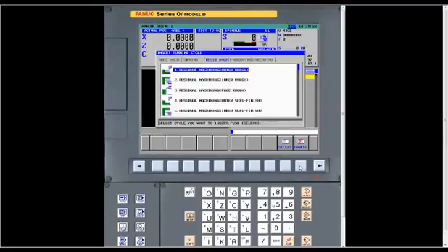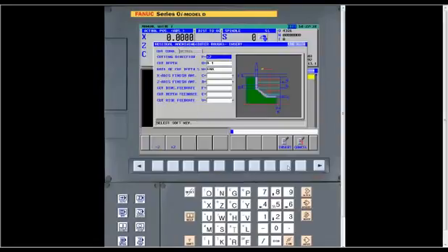The next tab is residual machining. And just to give you an explanation of what that is, say for instance we're turning a part that has a large relief that only one particular type of tool will fit into. What the software does, as long as you have your tools described right, it'll look and see if a tool has clearance to get into that relief. If it doesn't, it'll give you a little message saying residual stock will remain. That tells you that you have to go into this cycle and select that and fill in the blanks just like before. Again, it's got Z minus, Z plus, and it looks just like a rough turning cycle, exactly the same fields. And the software will actually then go take that tool in, the one that will actually fit into that profile, and go in and just take out the stock that's left. So that's residual machining. Again, as I said, it looks exactly like the other cycles. Just fill in the blanks.